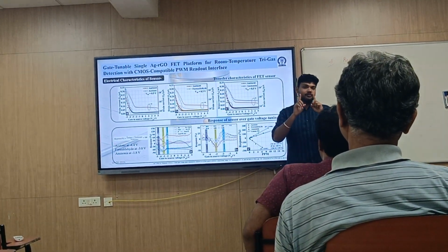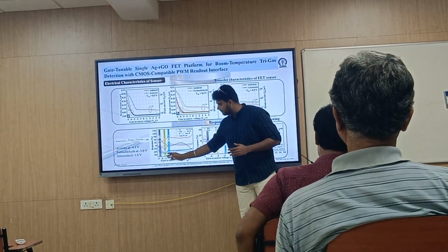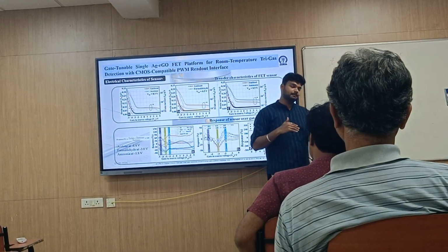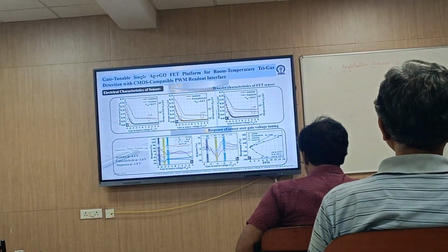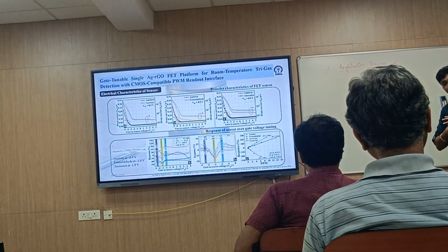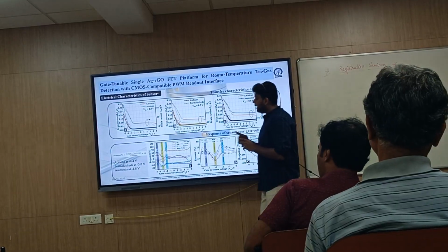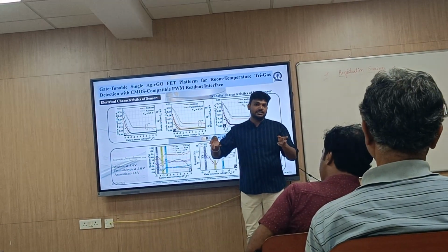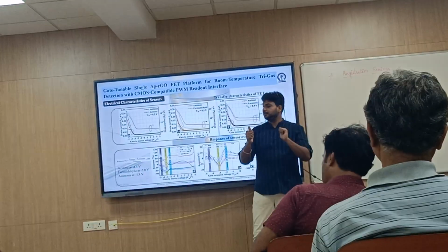Formaldehyde is a dip, and acetone and ammonia are peaks, depending on whether the gas is giving or taking electrons. So we try to detect three gases: formaldehyde, acetone, and ammonia. First I individually checked, then second I took a mixture.